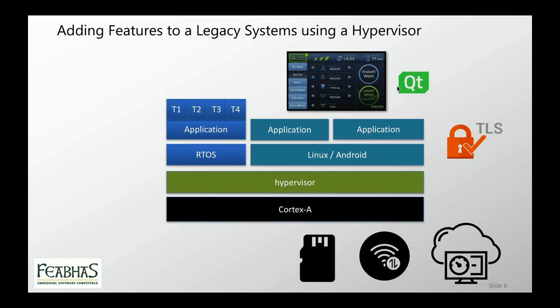But obviously anybody who comes from what I call a real-time background would still say, even with real-time Linux, we need to be aware of the model there. With an RTOS we have a very well-proven tasking-based model. We understand priority-based preemption, for example. So one good use of hypervisors is they bring in this capability where we can have isolation between the RTOS application and our general-purpose operating systems. But that allows us to utilize the rich nature of something like Linux.